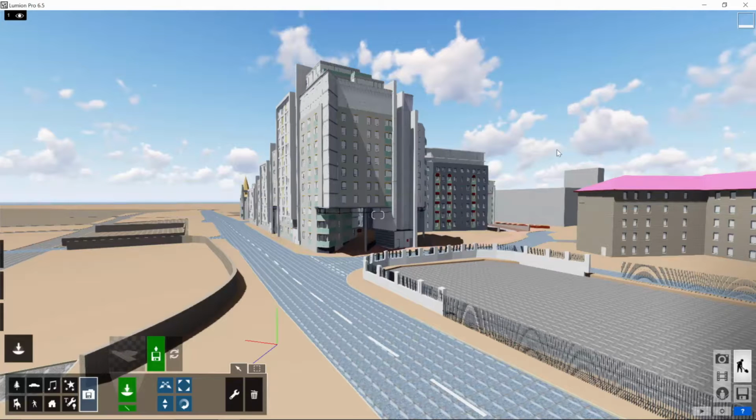This CAD model is complete, but we do have many users using Lumion who align it to their BIM process. What they will do is take their model into Lumion at the early conceptual stage, and as decisions are made and the design matures, they use the reload function in Lumion to update their Lumion scene. This will retain any materials previously applied, any people, cars, and any other objects you've placed in will remain intact. So it's quite a nice way to visualize your designs throughout the BIM process.